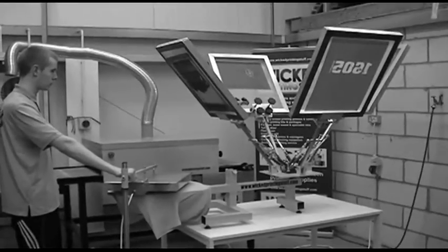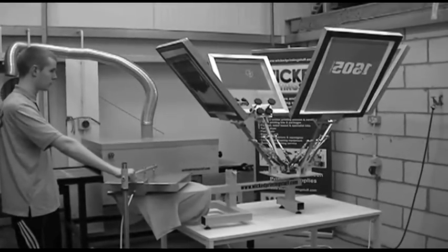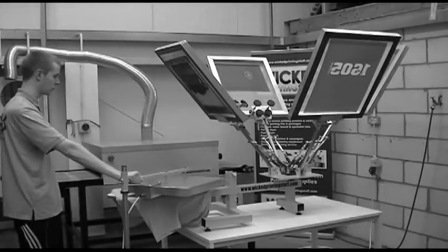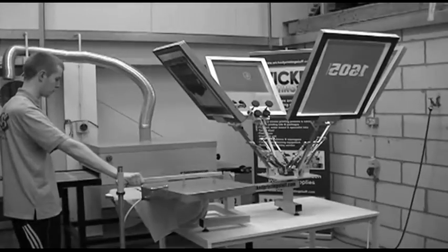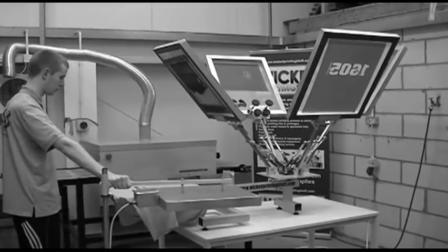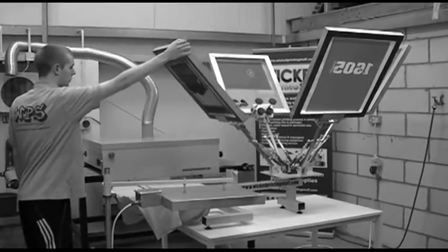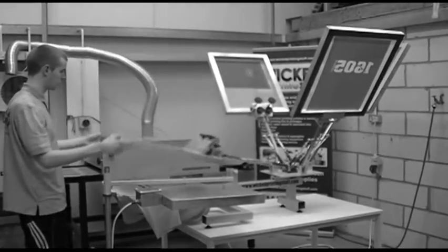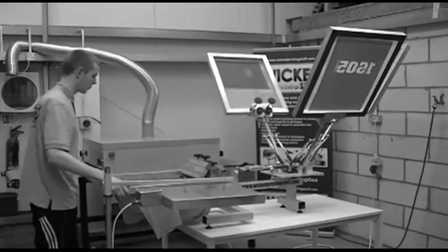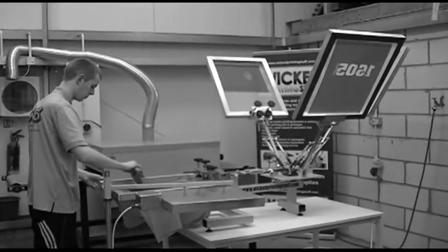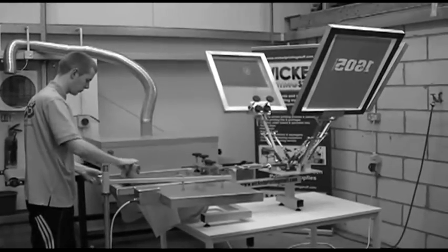Once you have finished your print, you will need to fully cure your garment. Simply drying the print does not mean that your garment is machine washable. In other words, the print will come out in the wash. Most Plastisol inks cure at 153 degrees. Wicked Printing Stuff water-based inks need to be cured at 180 degrees if a catalyst is not added. You can use a flash dryer, heat press, or tunnel conveyor dryer for this.